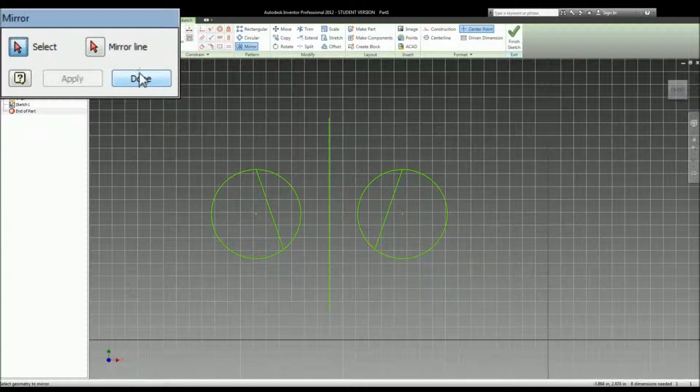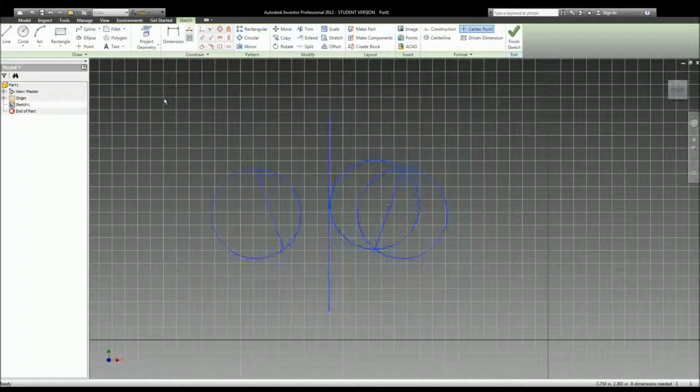When you mirror something, you have to be sure to specify where you want to mirror over. So let's say, again, I have the select option, so I want to select these objects. I want to mirror it over, say, this segment. Doesn't let you. Center point, nope. This line, yes, it does. And there you go. Mirrored this object over itself. It's very specific that you have to mirror it over a line. Okay, so I'm done with that and delete.